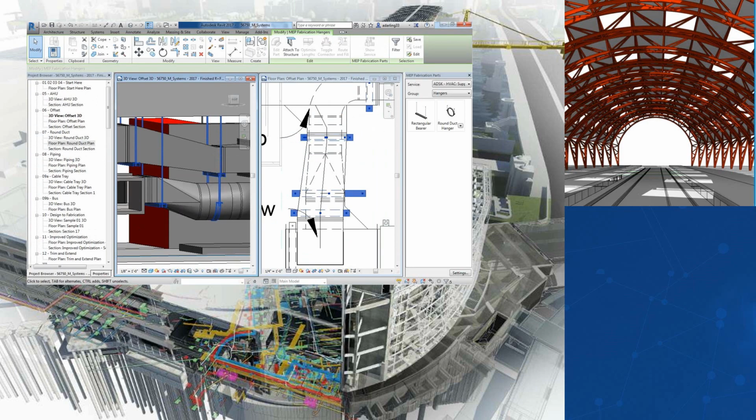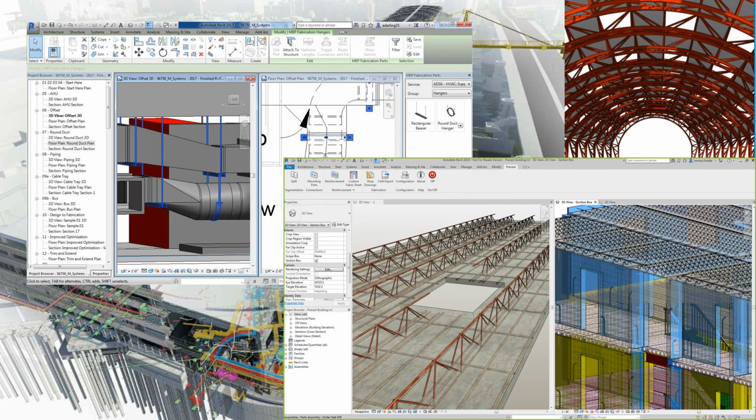If we start looking at the modeling of the MEP components, here you can see the difference in the display of the 3D versus the 2D, right? But essentially, it's still all the same objects in the same space. And of course, another aspect to have a look at, because I come from that structural space, is the precast elements, whether they're precast hollow core slabs, or solid walls cast off-site in beds and then shipped and installed on site, it really doesn't matter. There's a whole range of options available to you.